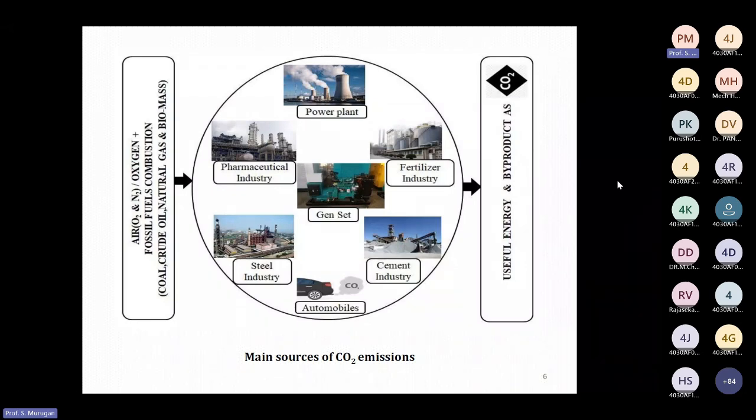But according to the amount of air supplied into the engine or into the combustion device, the carbon dioxide emitted by the combustion device may vary. If the combustion is more complete, then you will get more CO2 emission. If the supply of air is less, then you will get more CO, carbon monoxide emission. By the way, the carbon dioxide emission purely depends on the amount of air supplied, the quality of fuel, and the residence time for combustion, all these things.